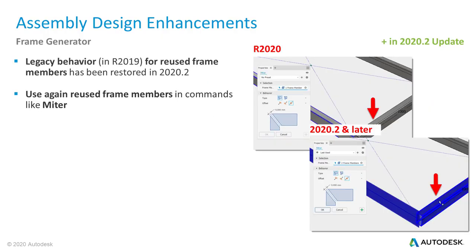In Inventor 2020 and 2020.1, we prevented including reused frame members since they are theoretically treated as read-only. However, in some cases, it is useful to be able to edit reused frame members, such as with the miter command. You get the legacy behavior back in Inventor 2020.2.